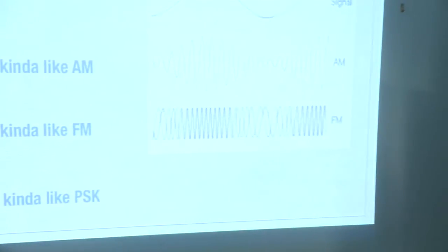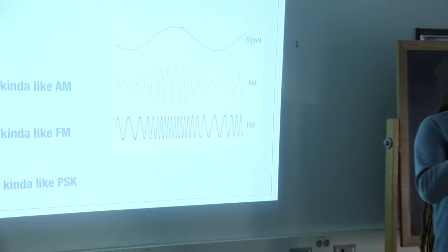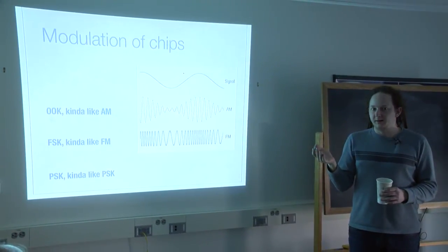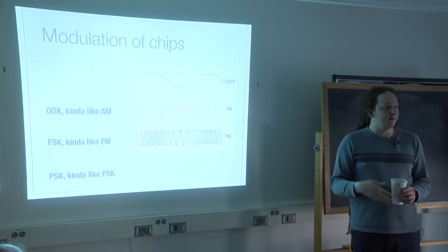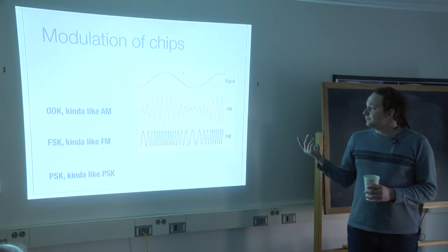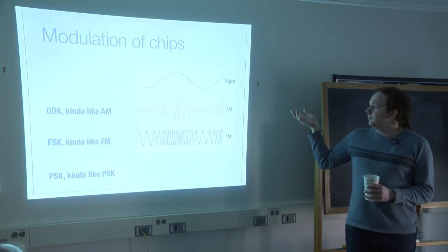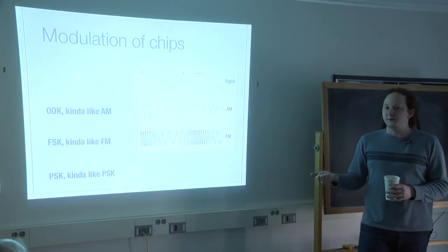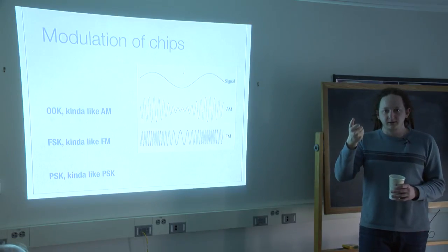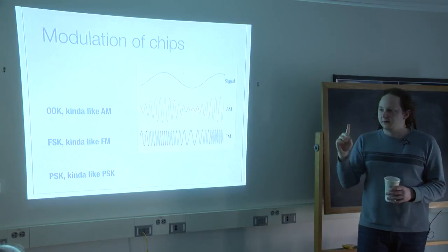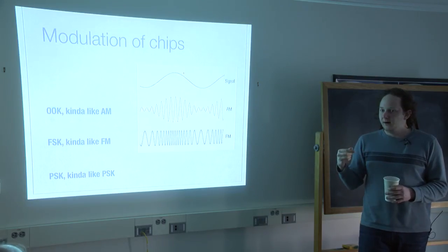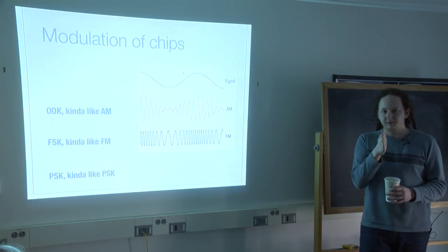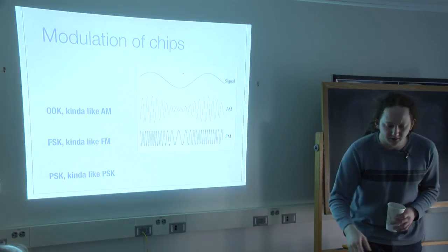So you have different types of modulation, and you can also play between these types of modulation by controlling a packet in one style and then using that to leak information in another style. The easiest one is on-off keying, which is kind of like AM. This is what your garage door opener will use. The idea is that to mark a 1, you turn the carrier wave on. To mark a 0, you turn the carrier wave off. And then you receive it kind of like AM, or kind of like you'd receive Morse code, in that you tune AM just a little bit off and it produces an audio noise.